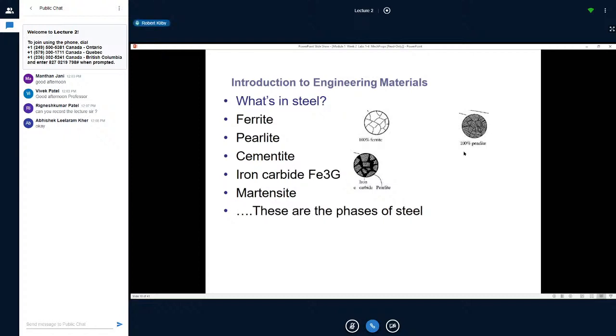As more carbon is added, since these little crystals are all saturated, it starts to fill in what's called the grain boundaries between the crystals. When it goes into the grain boundary, it's called cementite, also known as iron carbide. These are both the same item, just expressed a different way. But it starts to fill in the grain boundaries with carbon because these guys are saturated in the crystal.